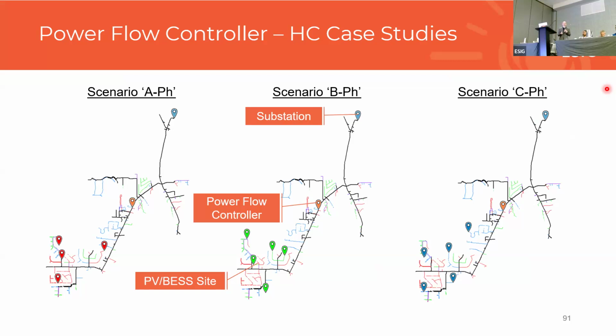But similarly, from a volt-var perspective, from DER, let's say, because many DER are operating based upon the average voltage measured, if you are running into a scenario where you're limited by one phase, you're essentially having to suppress the voltage of all three phases in order to mitigate that. So as you pull your voltages closer together, you don't have to consume as much reactive power.